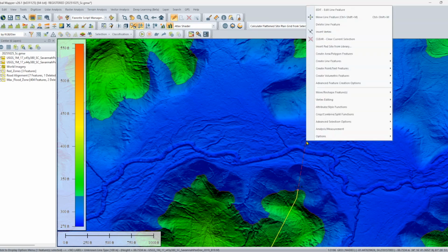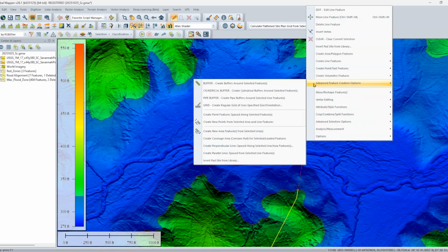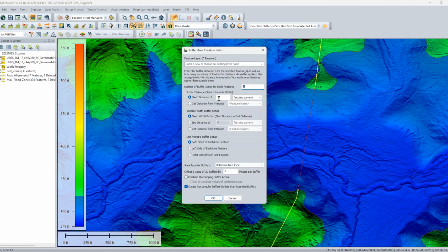Now that we have the dam center line, I'm going to create a buffer of 15 feet on each side of that line. That gives us a 30-foot top width, which matches the width of our access road. Think of this as the crest of the dam, the flat area you'd actually drive across. This way, the geometry of the dam and the road line up perfectly. So when we look at it in cross-section, everything makes sense. Here's a quick reminder of that road cross-section.